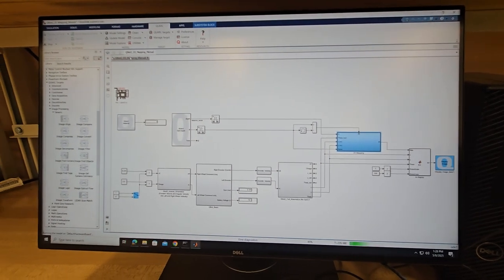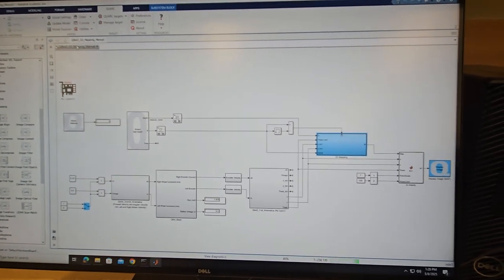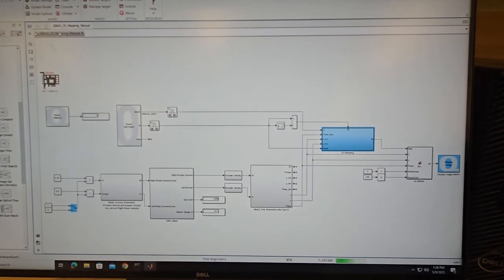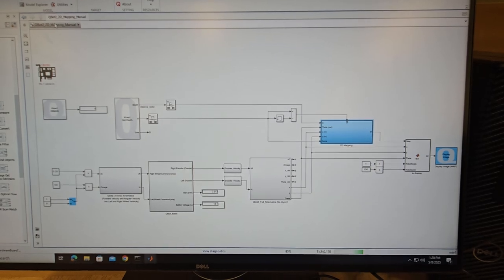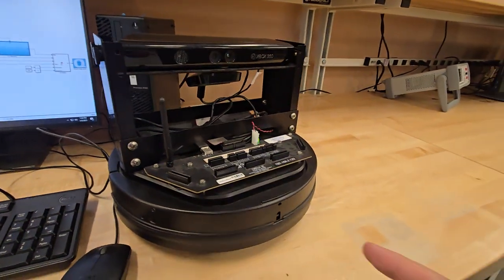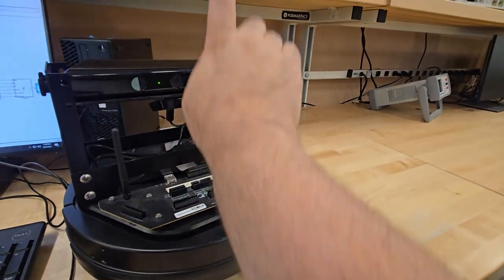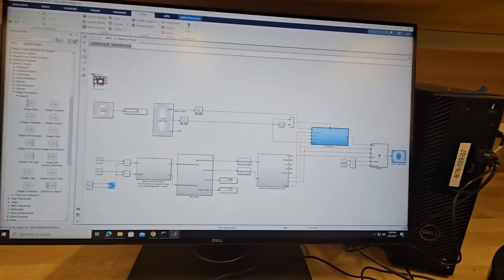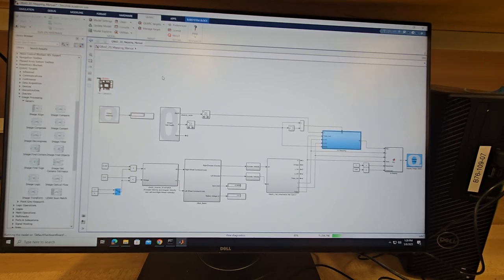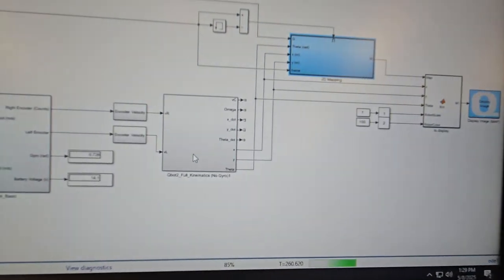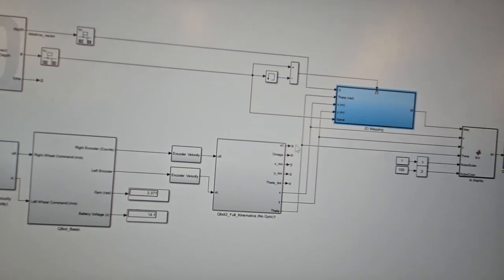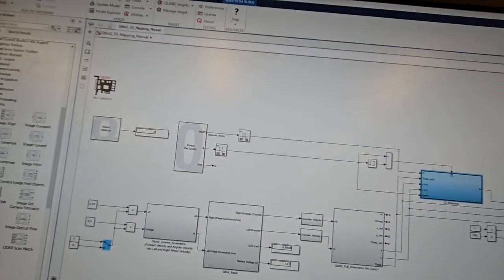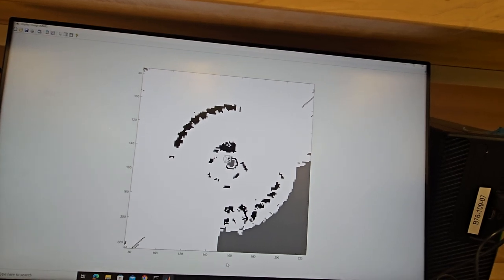One last thing before I finish the video, remember that when the robot captures the depth data, it is with respect to the robot's attached frame. X, Y, and theta. Remember, for a mobile robot, X is forward, Y is to the side, and Z is upward. But when you put those data together and create a map, you have to transfer them back to the world coordinates, and that's where you need that X, Y, and theta in order to transfer them back to the world coordinates at any position and orientation of the robot. Then you can accumulate them and you can get an occupancy grid map like this.